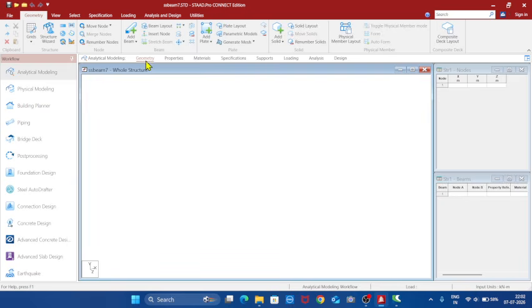So geometry is already highlighted, in which we have what is called the structure wizard. If you want to know about any particular icon in this STAADPro Connect Edition main screen, just move around the icon, it will display the purpose of the icon, unlike in other softwares. So here structure wizard, where we have standard templates of various structural models.